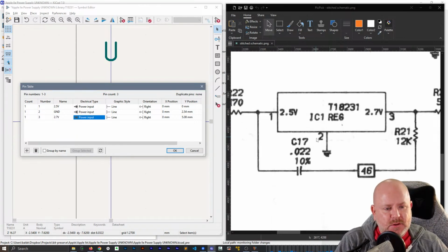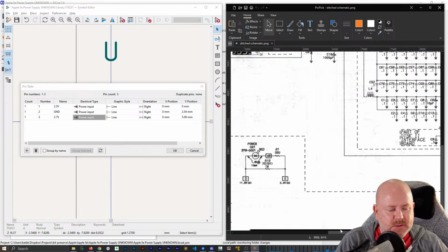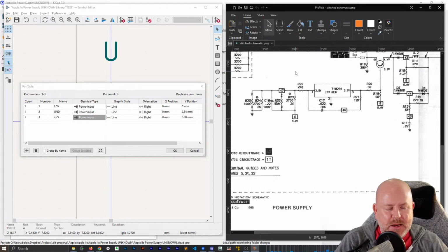And now we will try to look at this just a little bit and try to understand, what is this thing doing? Can I make a haphazard guess? See, there's this 5 volt thing going. This says 5 volts comes into here and goes through a 2.7K and a 470. That's in parallel with, well, that 100K is basically nothing.